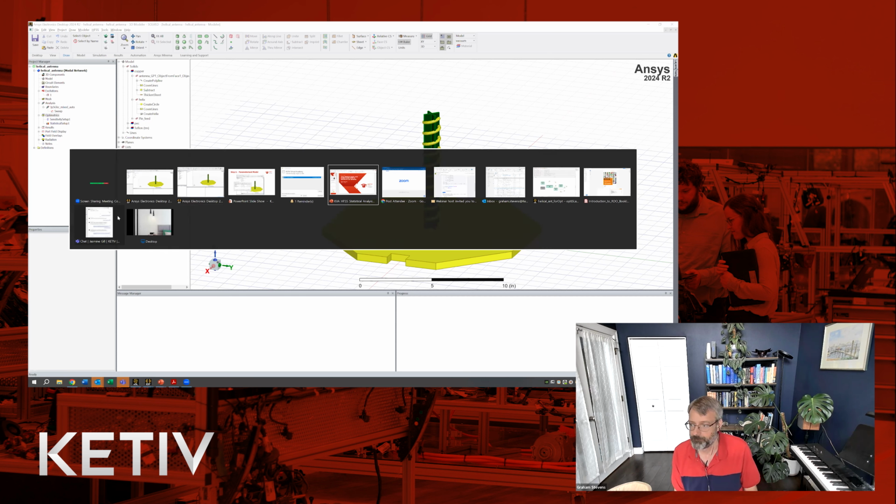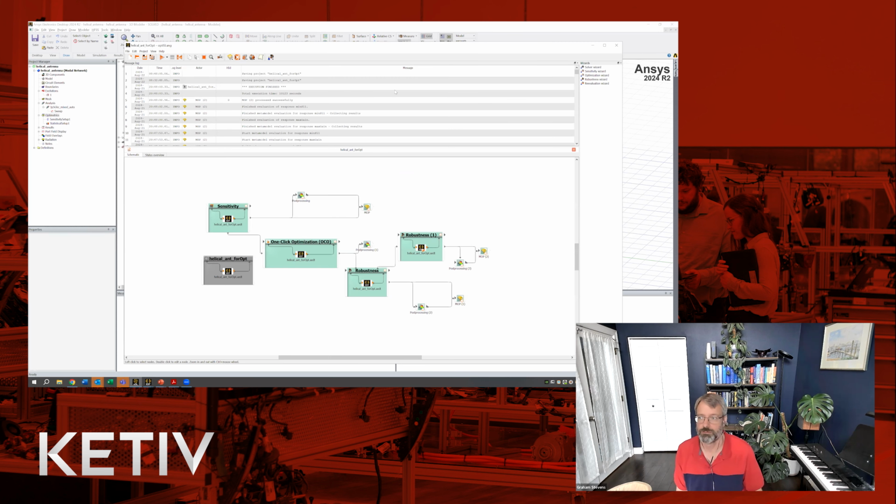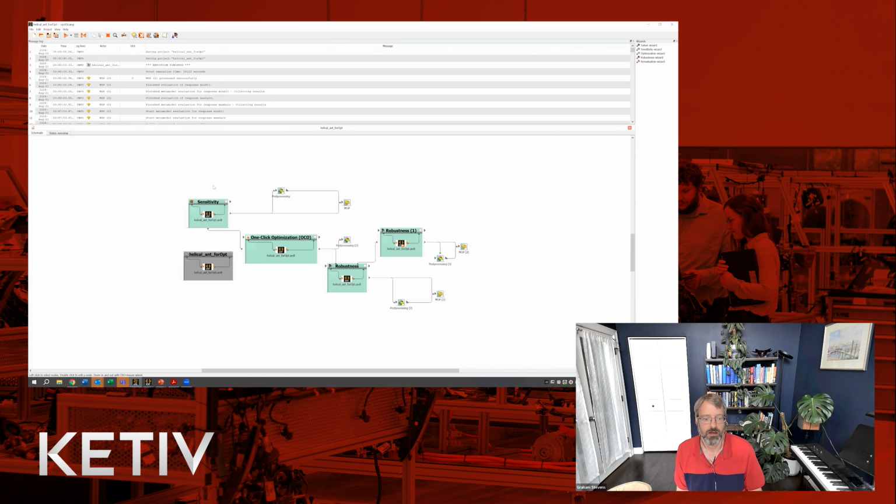If you go into Optislang here, we'll just switch to Optislang. In Optislang, to set up the analysis, you want to click on this solver wizard up here and drop it in, and then set your settings here relative to which variables it's pulling and so forth.